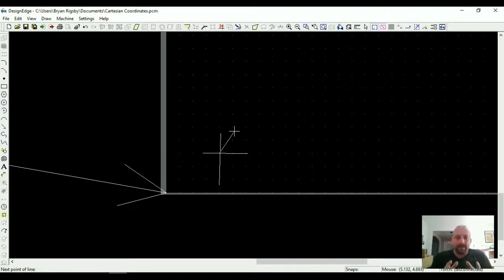From here, when you're working your way around a dimensioned part and entering it, you can start with squares and circles and where they fit, or if you have all the dimensions, just start at a corner and draw it around, because you don't have to enter absolute coordinates. You can enter relative coordinates. So from here, 1, 2, 3, 4 inches up would be over 4 and up 7, right? So 1, 2, 3 to our spot, and then 3 plus 4 is 7. 1, 2, 3, 4. So if you want to do all that math, you can.